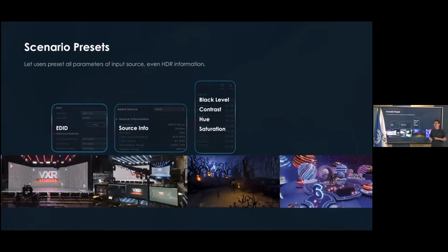Before, you needed to set the controllers one by one, whether you had 10 or 20; you would need to set it 10 times or 20 times. Now, if you group them together, select the group, and just set it once, all the job will be finished. And even here, you can set the HDR parameters for all the controllers. With the new solution, for the HDR part we also support HDR 10 bits with 444 format, and the PQ mode is also supported here.